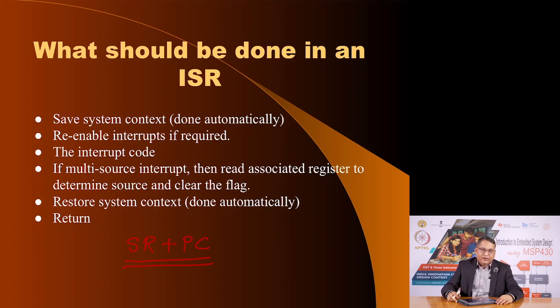Now, once you enter an interrupt subroutine, the global interrupt enable bit is turned off, which means no interrupts can happen during the execution of this program. But you as a programmer and a designer are free to enable the interrupts, which is what we are saying here. It is possible to enable interrupts within the interrupt subroutine, and I would advise you to exercise great caution in trying to re-enable interrupts within the interrupt subroutine. Of course, what would come after that is the actual program that you would execute in the subroutine.